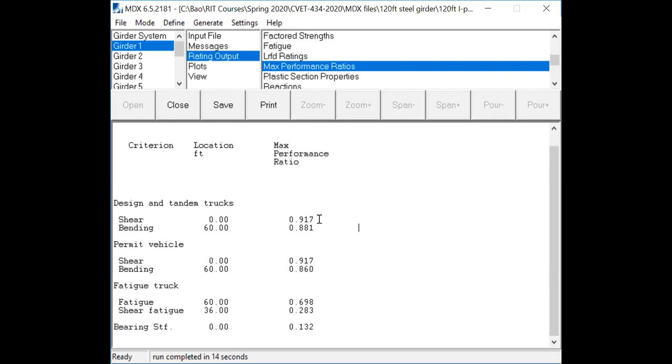And also we want this performance ratio not significantly lower than 1, like 0.3, 0.4, things like that. And 0.5 means your design is too conservative. We want to target the maximum performance ratio ranging from about 0.6 to 0.99, and that range is the best. I would say the best design is around 0.7 to 0.9, that range is the most reasonable design performance ratio, 0.7 to 0.9.